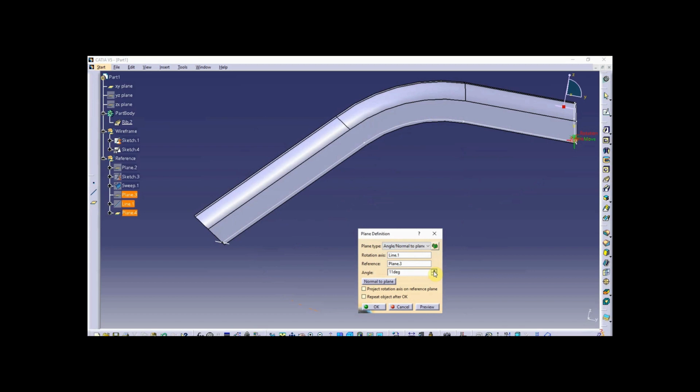So I will trick my students and say, one of the options, the keep angle keeps the profile normal to the center curve, which is incorrect. It keeps it at the same angle throughout. So right now I'm sitting here at an 11-degree angle, the profile to the center curve, so it keeps that 11-degree angle all the way out, all the way through the sketch, all the way through the sweep. So very important concept. I wanted to demo that to you. I want to back this up to be back to 0.